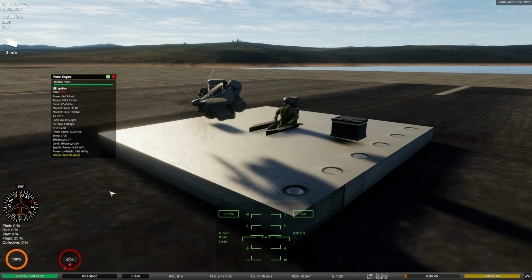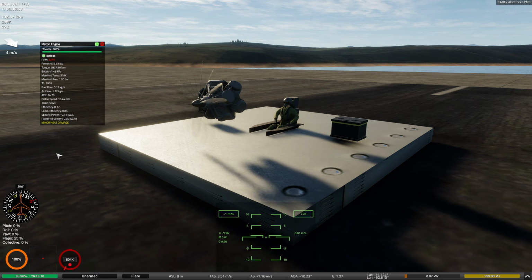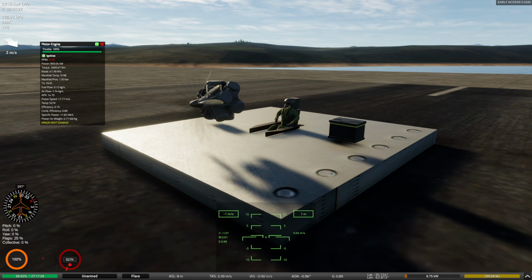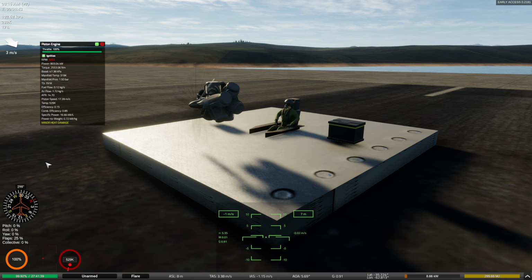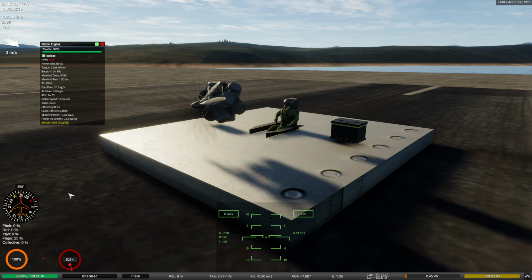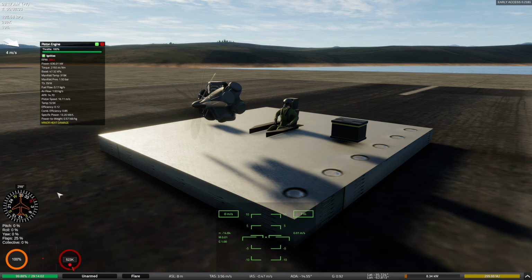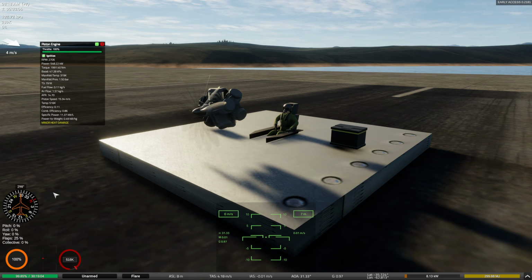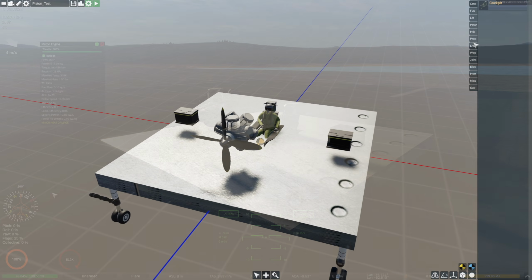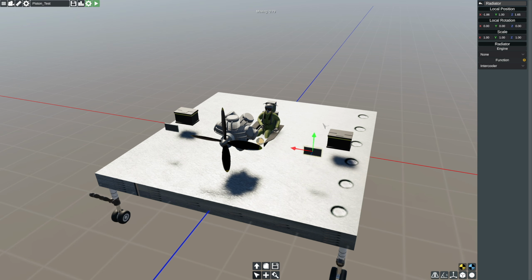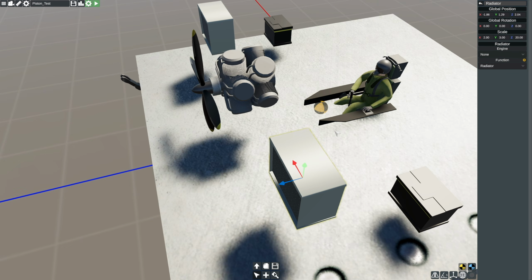In addition to preignition, you also need to consider the engine temperature. At about 457 Kelvin, the engine will start overheating and then take heat damage. Heat damage will make your engine's performance deteriorate, and higher engine temperatures will make the damage level worse. Overheating is generally caused by high compression ratios and having an engine with a very high RPM.